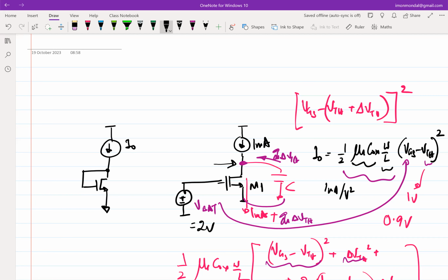So once this voltage decreases, when will this stabilize? If I neglect channel length modulation, when do you think this will keep on happening? Will this keep on drawing current out of the capacitor and the voltage keep on decreasing? So this voltage here, whatever it was, will ramp down, because GM times delta VTH is constant.